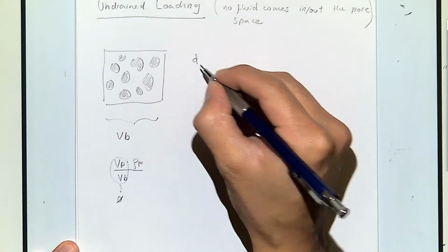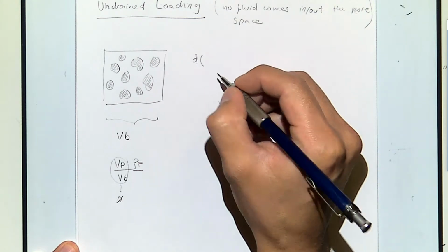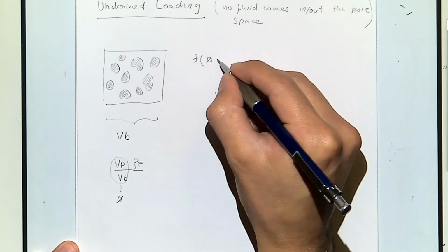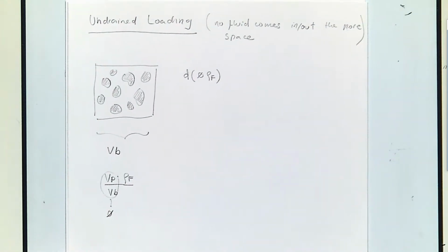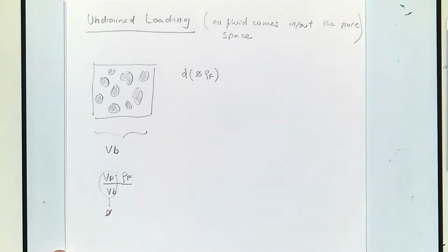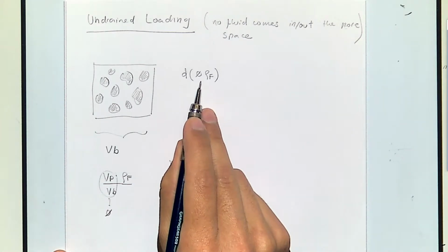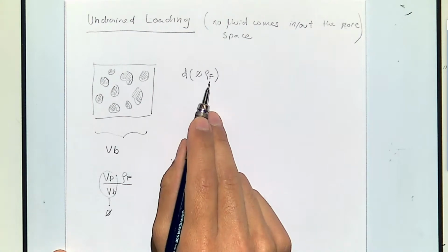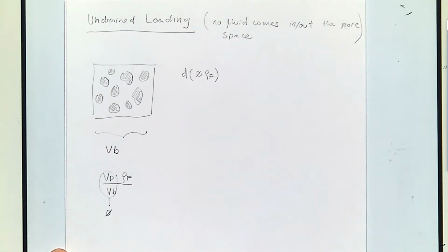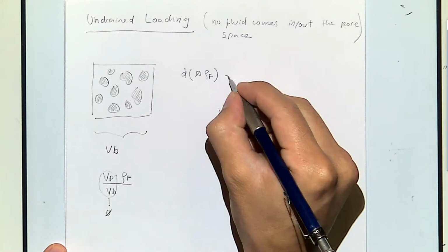We're going to work with this equation in which we want to understand what is going to be the variation of mass of fluid per unit of pore volume by either varying the porosity inside the porous solid or by varying its density. Here we don't make this assumption of incompressible fluid flow anymore. Now we have a compressible fluid, we have a compressible porous solid. All right.